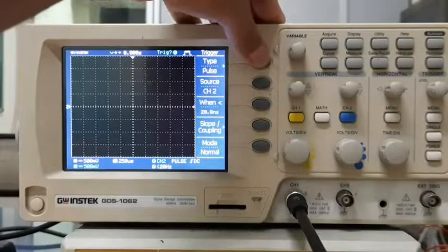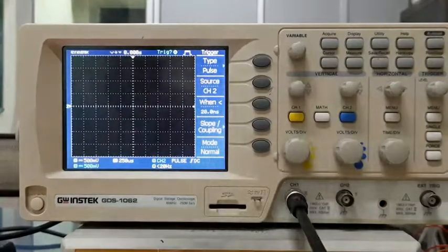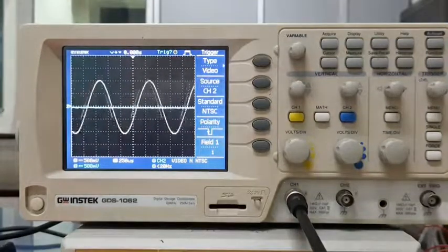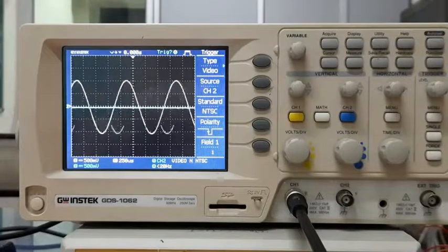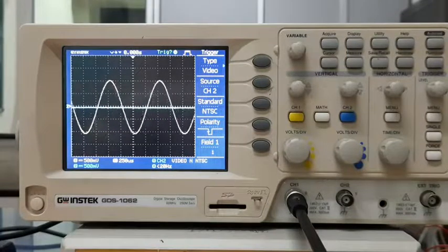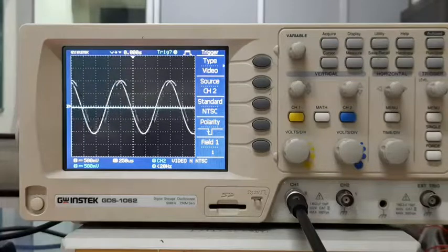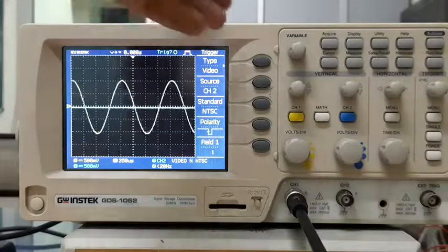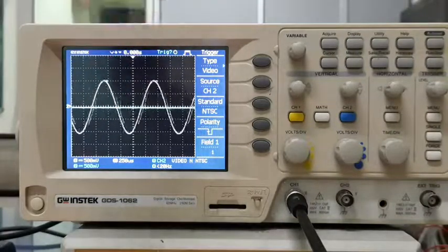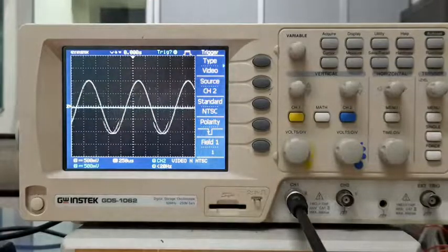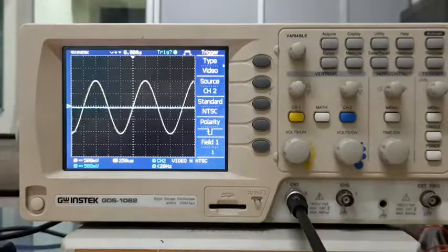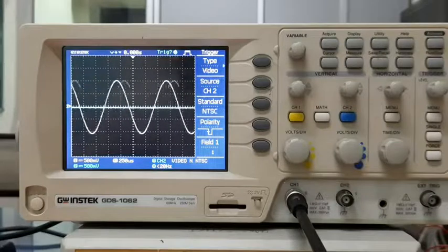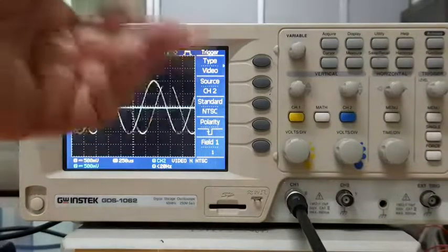It can have a pulse, right? So normally if you have a periodic signal, then you select edge type. But when you have pulse signals, you select the pulse. Right? You can have a video, and video is basically a continuous trigger, but it's very hard to then set it to the same periodicity as that of the external input, right? And you can see that as soon as I set the oscilloscope internal trigger, then there's something coming. But that's what will happen when you don't have a proper trigger set, that you will see this periodic waveform, but its periodicity is not correlated with the refresh rate of the oscilloscope, and that way the signal appears here and there on that horizontal scale, right?